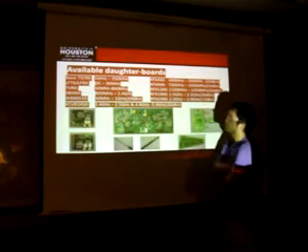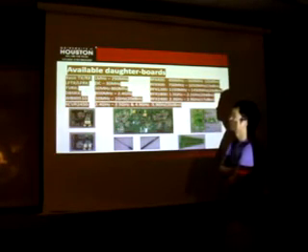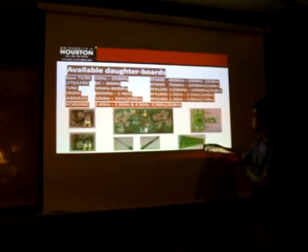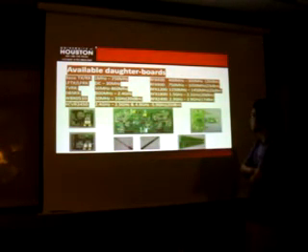It supports the frequency from 2.4 GHz to 2.5 GHz, and 4.9 to 5.9. And this one is for wide spectrum communication. It covers the spectrum from 15 MHz to 1 GHz. And these three are some antennas. This one is the directional antenna.